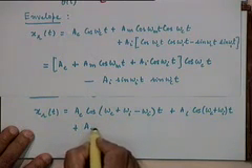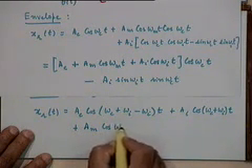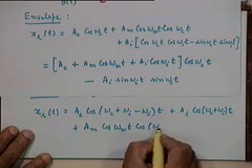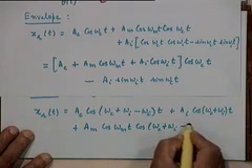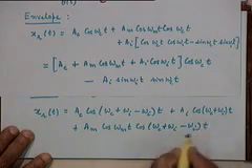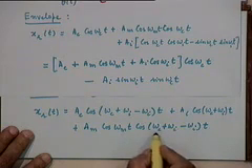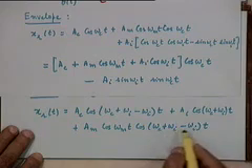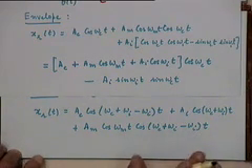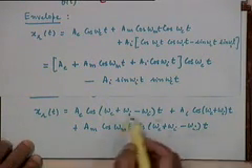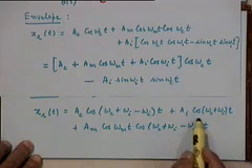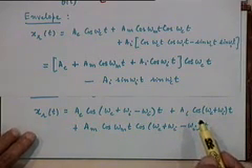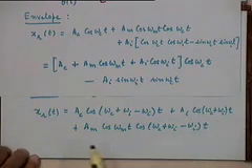And then A sub m cosine omega mt, this is the modulated part, into cosine omega c plus omega I minus omega I t. Same thing. Everywhere where I have only cosine omega c, I am replacing it with omega c plus omega I minus omega I. I think you probably already know what I am trying to achieve. I am going to write an expression in which the carrier is not omega c, but omega c plus omega I. That's basically what I am trying to do, and the reason will become very clear.